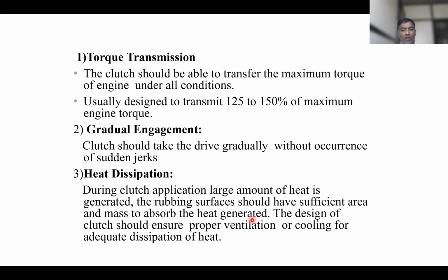So that is one aspect. And the design of the clutch should ensure proper ventilation or cooling for adequate dissipation of the heat. Whatever casing is provided to hold the pressure plate and the spring arrangement, or whatever arrangement is required to put external force on the clutch plate, it should have a proper ventilation and cooling arrangement.